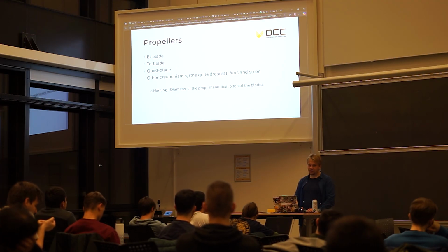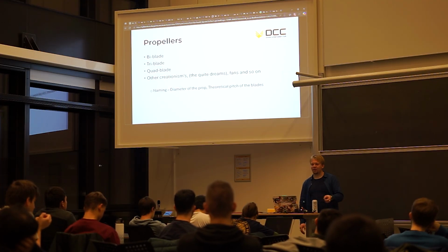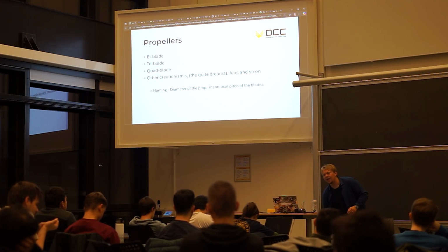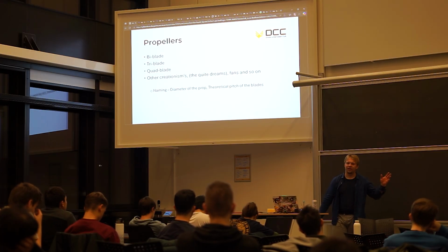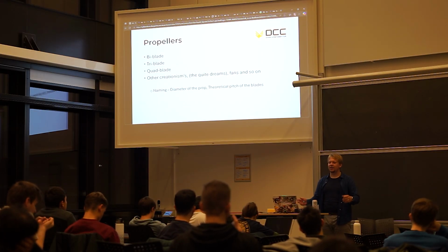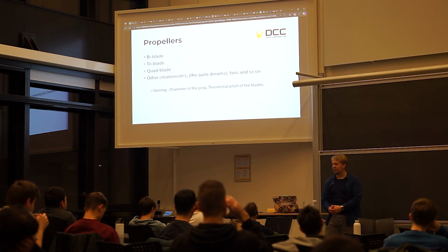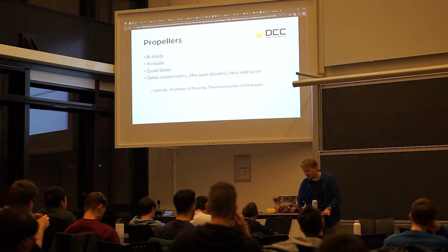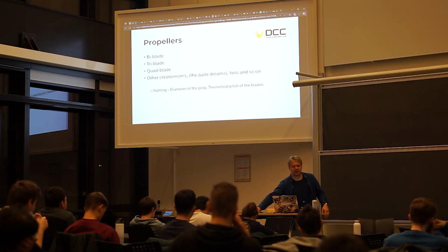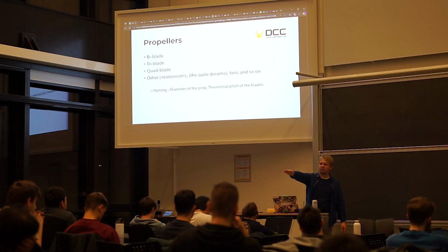Propellers have to be balanced. That is the main thing. If they aren't balanced, it doesn't matter how good they are. And if they aren't balanced, you might get a lot of different issues. Well, they will seem like different issues, but it's actually just an unbalanced problem. So I quickly wanted to show the diameter and then you have the pitch. Pitch is basically how much of an angle of attack it has.